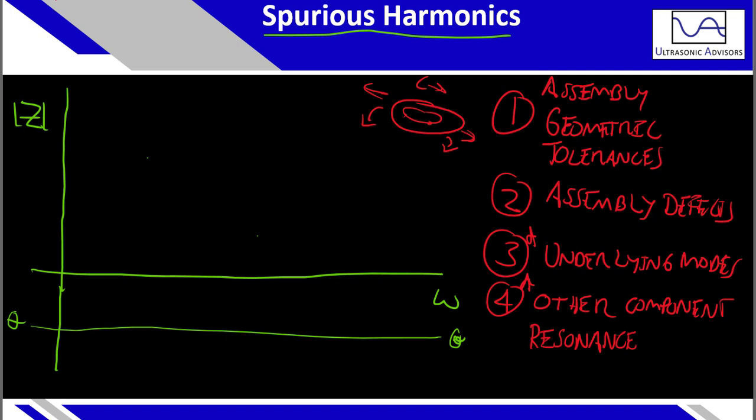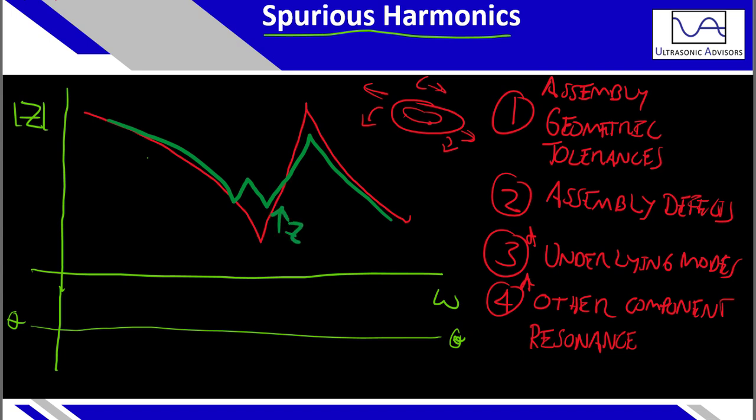So what will actually happen? If you have a device, even two devices, without spurious modes, let's say this is the first one, no spurious modes. And then we have another one with spurious mode. Typically what happens is that the coupling becomes worse. Like the impedance is higher. That also consequently means a lower real admittance. You wondering where is the resonant frequency here? That's another question that comes up at this point.